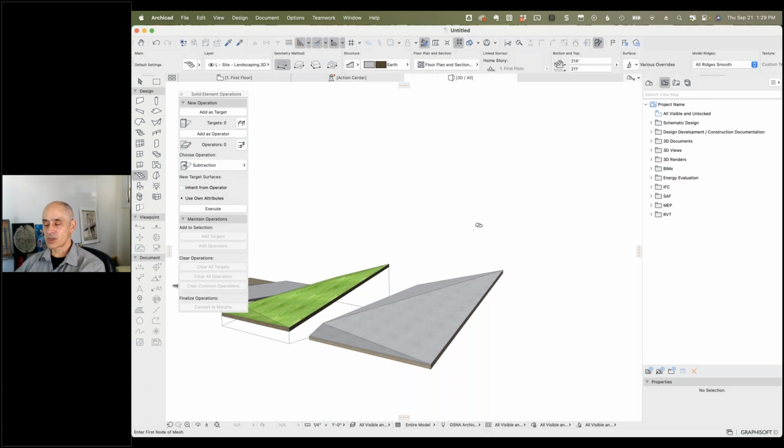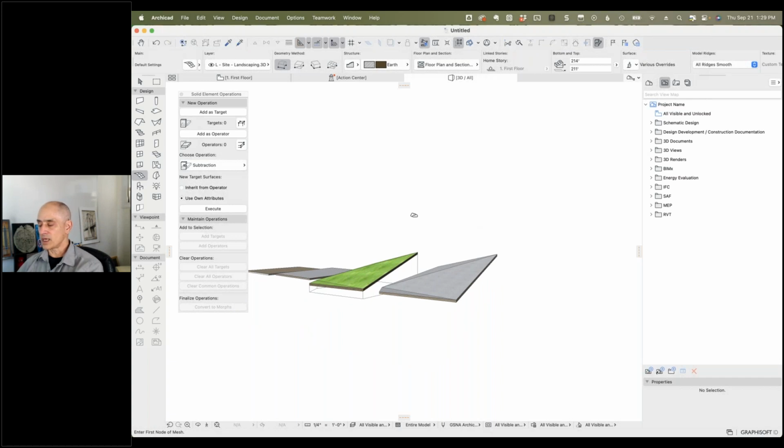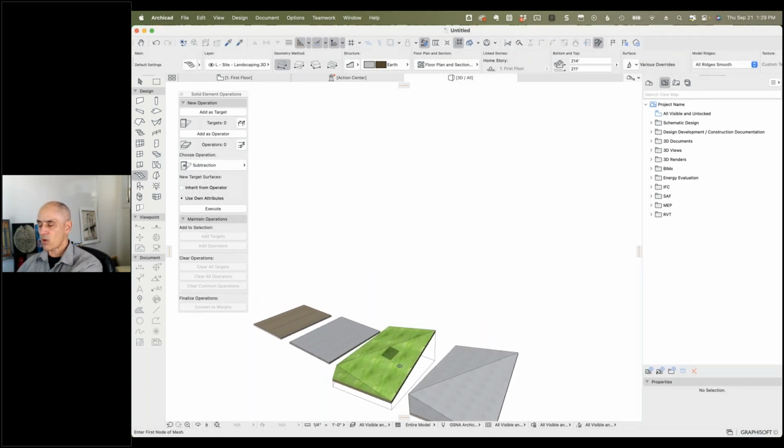One of the things about roofs is, as I was mentioning, you can specify a slope. So if we wanted to do the inverse, which would be to say, hey, I want to do some complex shapes and know what the slope is, you could do the drainage slope for multiple places and then just tell it, hey, find the intersection, find where these are going to meet and where it's going to have the low point, etc. So I can demonstrate that. It'd be the inverse, essentially, of creating roofs going up from the side of the building and finding their ridge line and hip and valley lines.